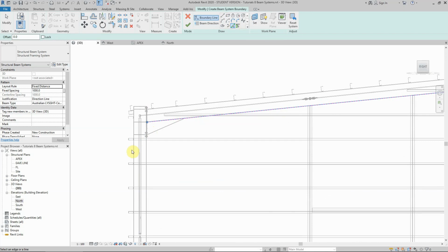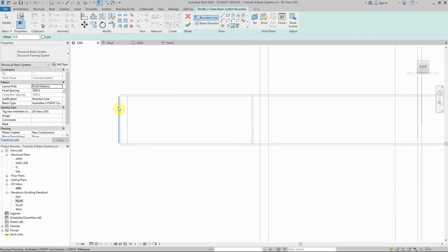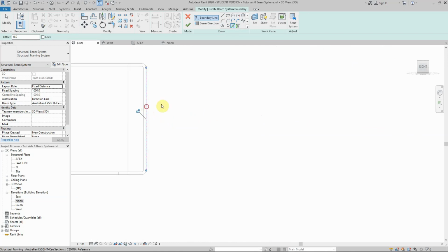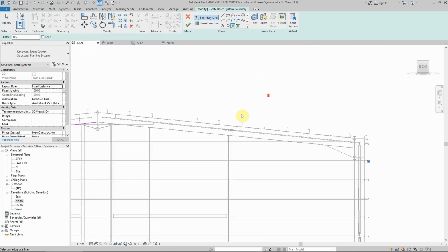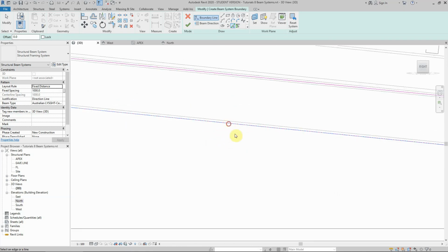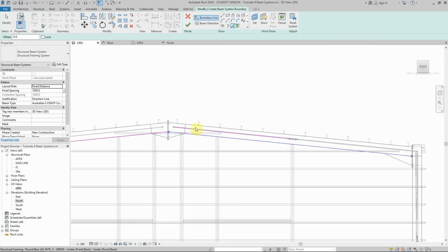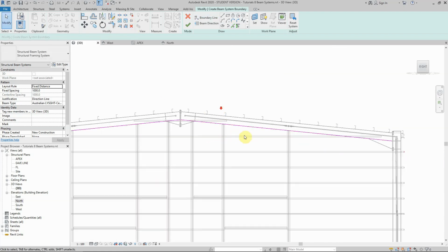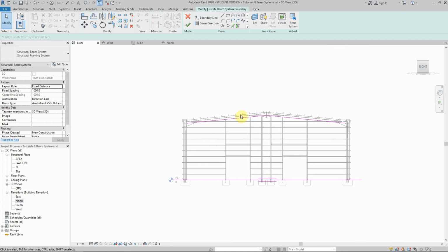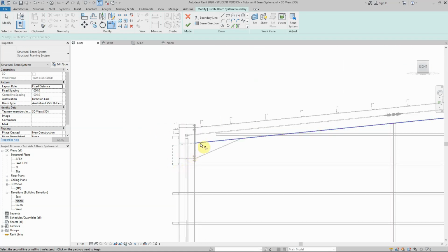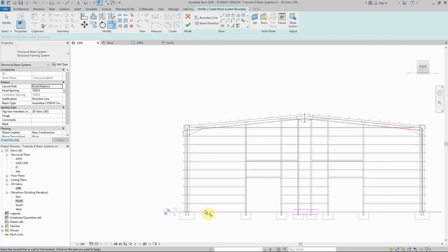So I want this to from here. I'll just choose from here this time. Maybe I'll choose a line from here, a small line from there. It's just choosing a group of lines. Okay, we chose that, so I'll choose this, I'll continue with that. I'll delete this extra line. Always when you have extra lines, that will create issues for you, so make sure whenever you draw a line that you don't need, you delete that. Trim and extend this small line here to connect there and there.